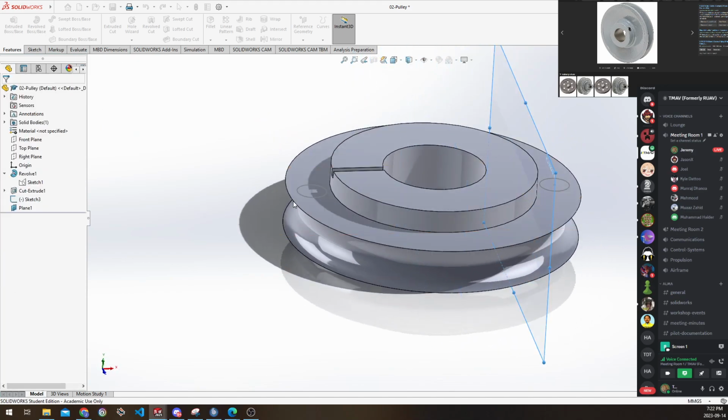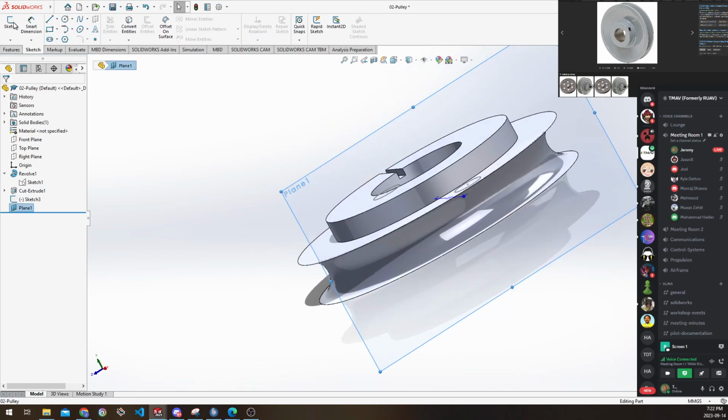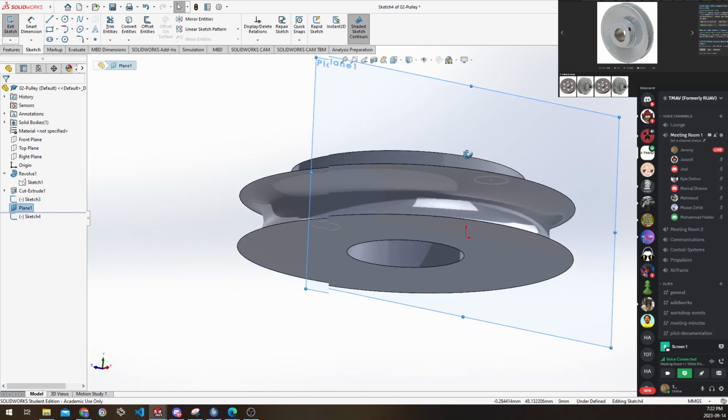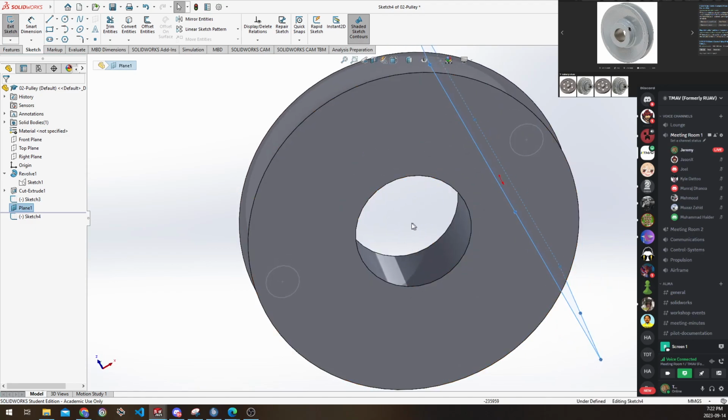So that's offset by 60 millimeters, and now I can use this plane for any drawings I want, right? Say I want to make a new drawing, I can make that drawing on this plane now, instead of in the center. You'll note that the origin of my drawing is the projection of the part's origin onto this plane, right?